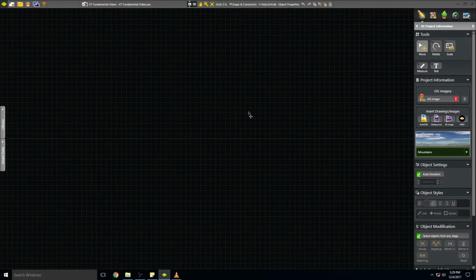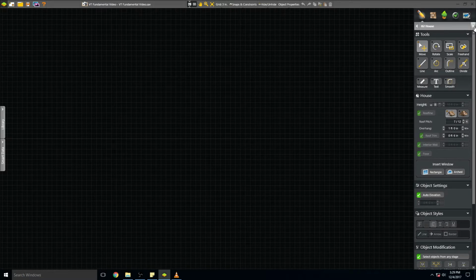So we're really going to move forward past Stage 1, project information, and go to Stage 2, house, and start drawing the house. Go to the top left-hand corner of the panel menu, and to the right of Stage 1, project information, you're going to see a little white triangle. Left-click on that one pointing to the right, and that's going to take us to Stage 2, house.